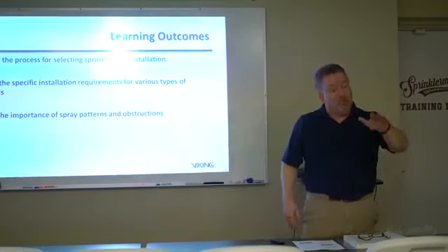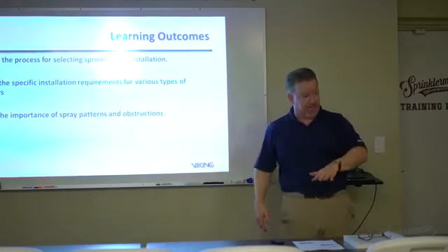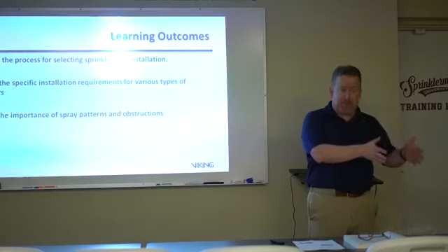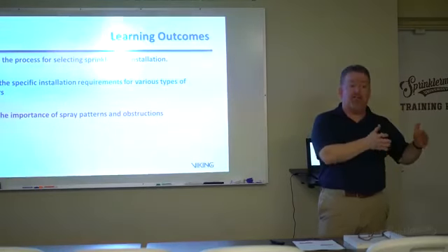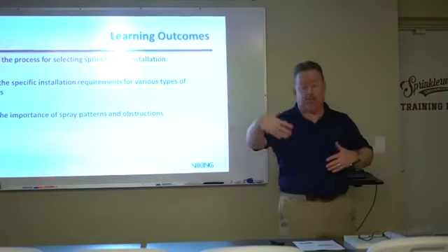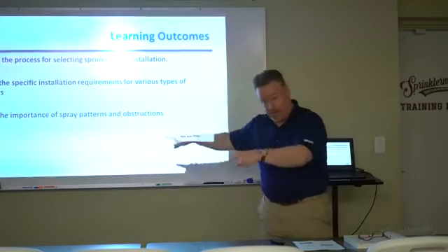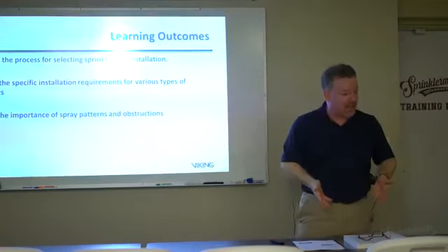However, what you do need to look at is what design criteria you used. If this particular sprinkler system was designed for delivery, remember we talked about the actual delivered density this morning, 0.1 gallons per minute over that, that was for a light hazard occupancy.